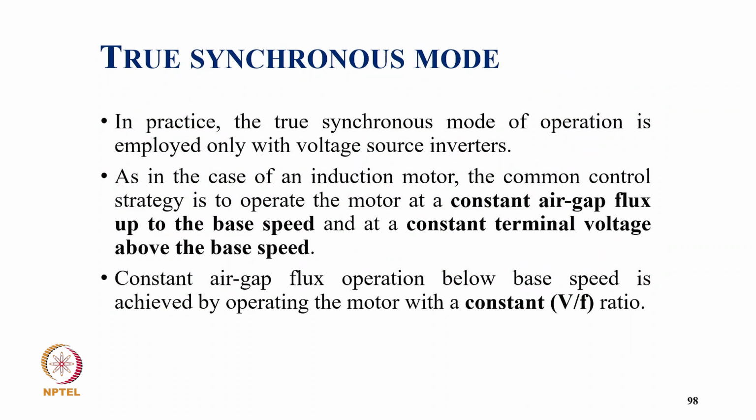In practice, the true synchronous mode of operation is employed only with the voltage source inverter, and as in the case of an induction motor, the common control strategy is to operate the motor at a constant air gap flux up to base speed and at a constant terminal voltage above the base speed.